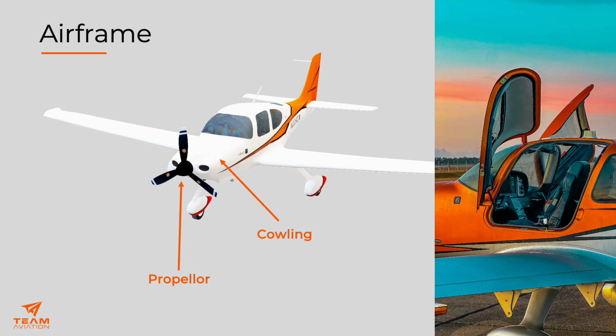The propeller, this is what generates thrust, pulling or pushing the aircraft forward through the air. It works by creating a force by accelerating the air, just like an aircraft wing, to produce motion. The cowling. This is the outer covering of the engine. It serves several purposes. It aids in the aerodynamic properties of the aircraft, protects the engine, and directs airflow to keep the engine cool during flight.